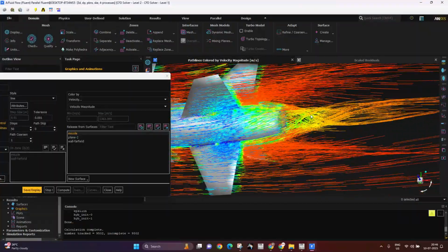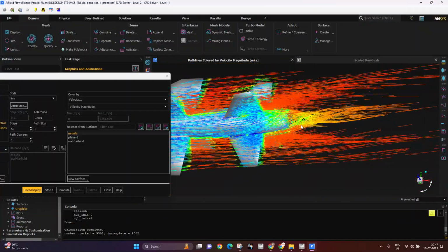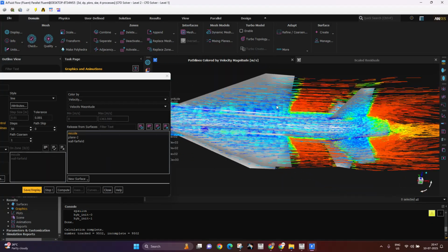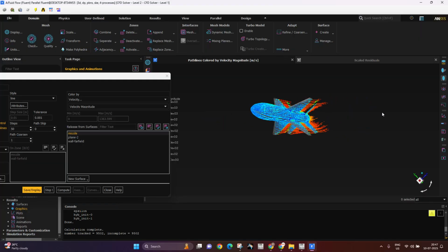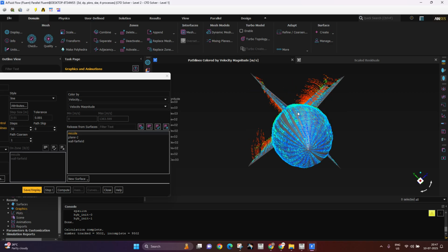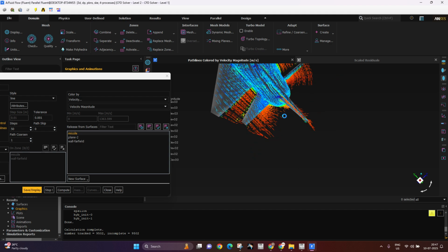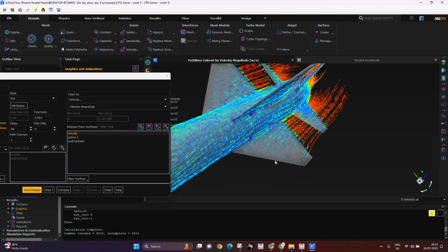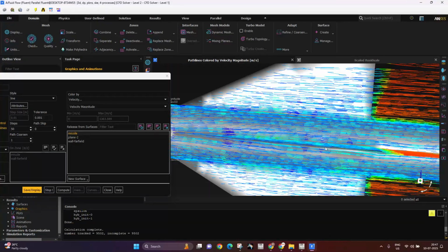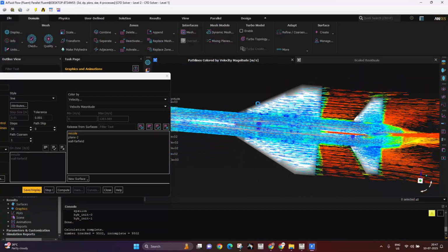So this is the stagnation point. So in this method, you can try figuring out where the drag is more, where the vortices are more, and you can try eliminating it by changing the design. So here I have given a wedge airfoil. The airfoil you're seeing right now is a bi-wedge airfoil.